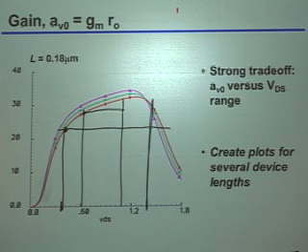Okay, now how about for V star? That one's a little bit more of a trick question, by the way. You picked that, right? All right, well, yes. Typically, I already picked that ahead of time. And as we'll see later, the way I typically picked that ahead of time was by deciding, well, I roughly know what speed my circuit is supposed to be operating at. Based upon that, I can come up with a pretty good guess what the V star needs to be. So once you've picked the V star, you're just going to pick the shortest channel length you can that meets your gain over swing specifications. Does that make sense to everybody?